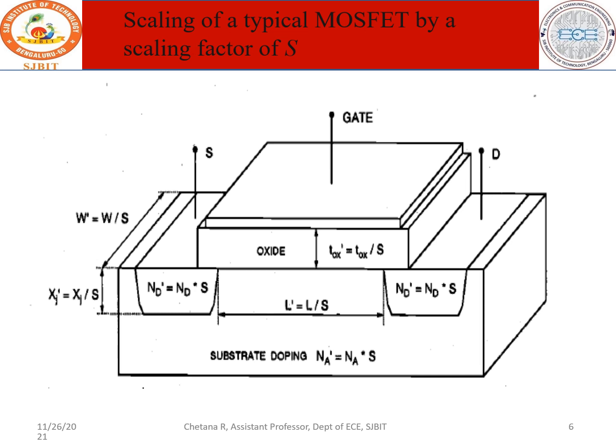This is the front view we are familiar with. In between the channel, you notice there is an oxide. Above the oxide, you have the gate. Please try to visualize this diagram. From the diffusion, you pull out the lead, that becomes your source. From the other diffusion, you pull out the lead, that becomes your drain. And as a whole, the entire chip is identified here with respect to the channel size. So the channel size is L.